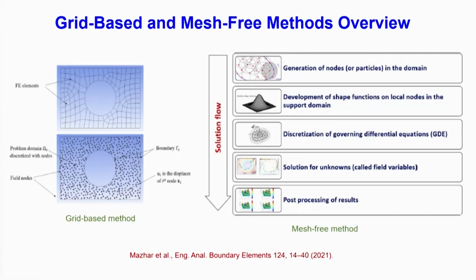So, you get a broad overview of grid based or mesh based methods and meshless methods. Typically you have some elements, maybe finite element, as an example you can also have finite volume, control volumes. So, you have a domain in the fluid, you have a domain in the solid, and you have a boundary, and by some way you either move the points in the boundary, or you do not physically move that, but by some other way you reconstruct the boundary at every iteration.